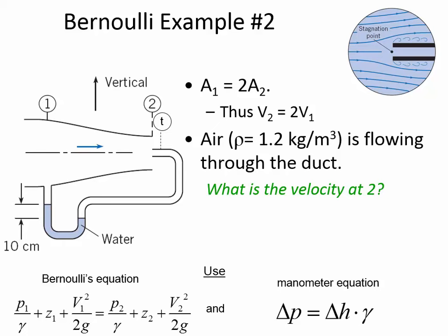And so let me give you a small hint before I give you some time to start working on this one and thinking it through. The first thing I'll tell you is that we apply Bernoulli's equation through a fluid, whether it's a gas or a liquid, but point 1 and point 2, we should be going through the liquid. So those 2 points, you can't go partly through air and partly through water. And so in this problem, we're going to assume that 1 and 2 are at the center line, and then we're also going to consider the conditions immediately inside the tube.